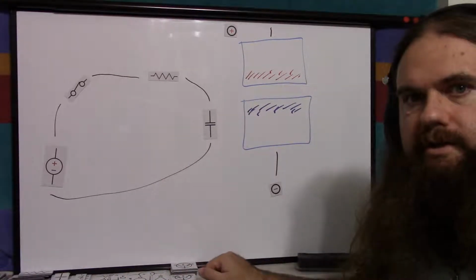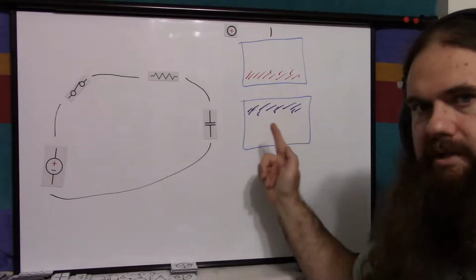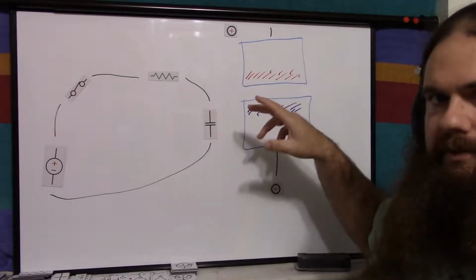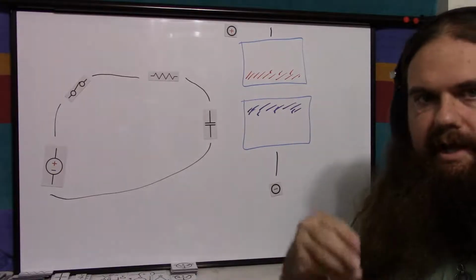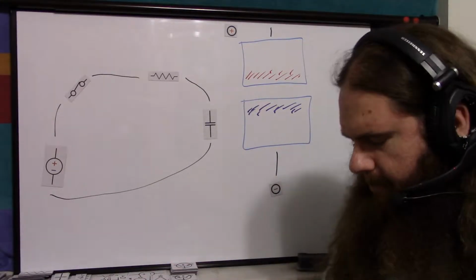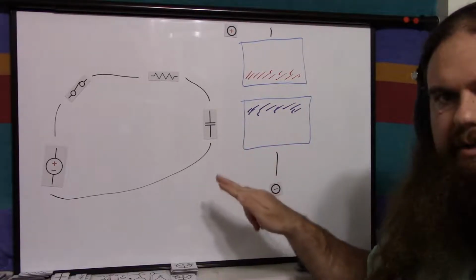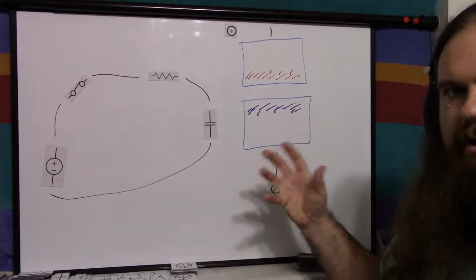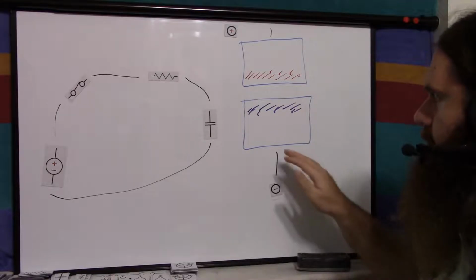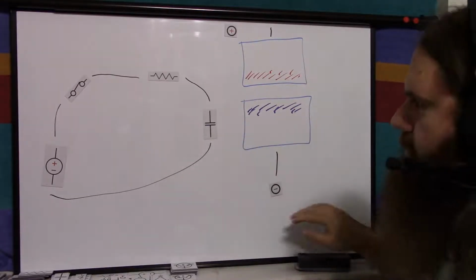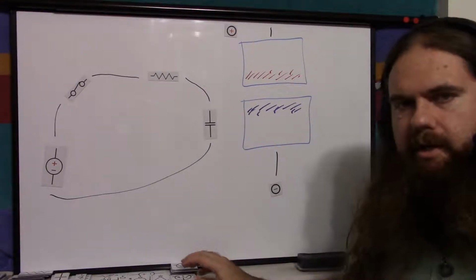And it does discharge naturally over time. Some electrons sneak across, and some of them bounce away. Some electrons get in there and stay, and so over time, it does discharge. But the point is, you should be able to see that the more electrons get shoved into here, the harder it is to push more in. You need more voltage because there's already a bunch. So what you get is a diminishing charge.